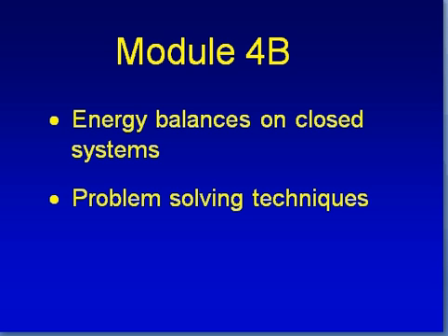Piston-cylinder allows for work to be taken out, and also because the boundary moves. Remember earlier we talked about the integral of PdV was the work out of the system, because the boundary is pushing back some force external to the system. And also heat can come in and out. So we have a closed system, meaning the mass stays in the system, but heat and work can come in or out of these systems.